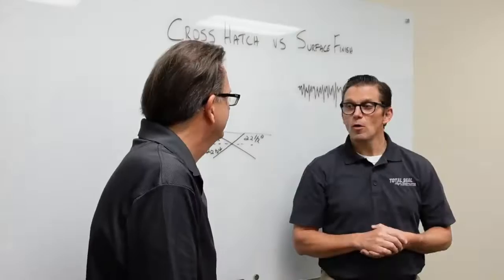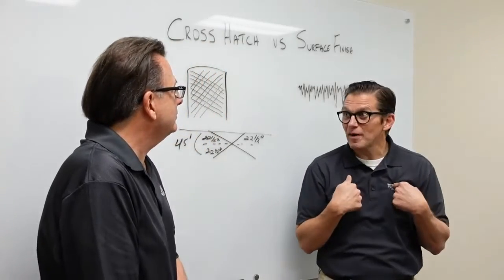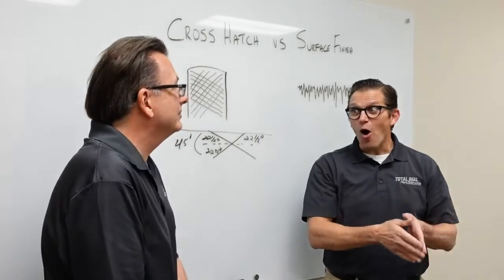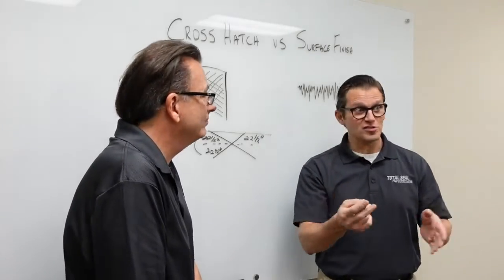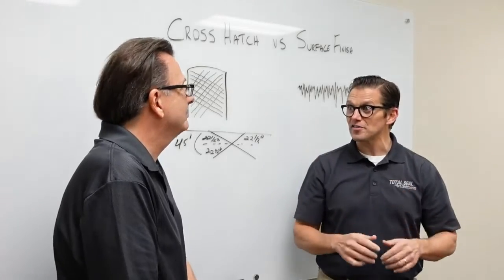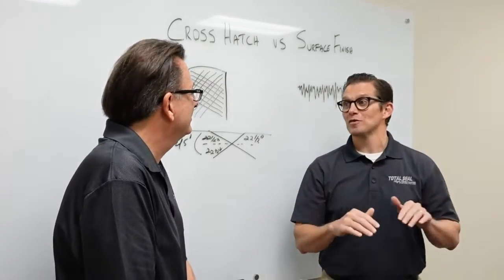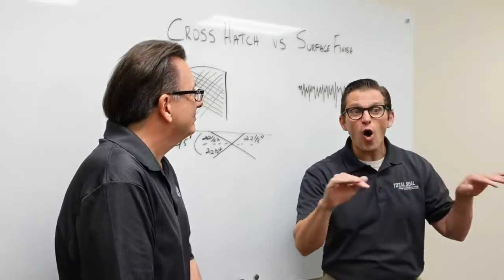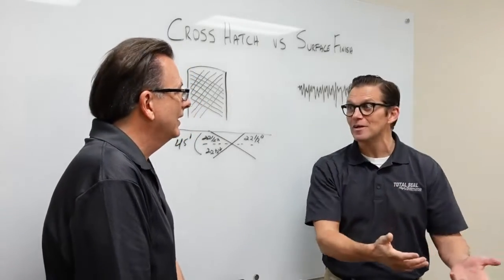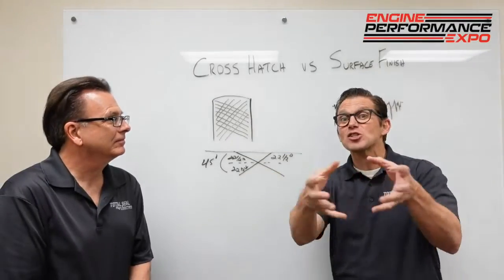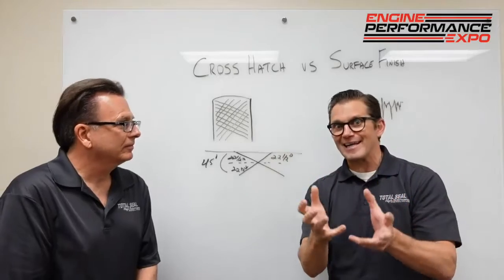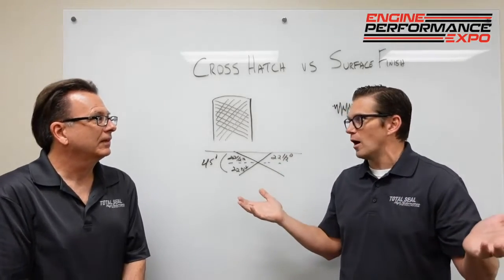This is about education. Like I said, my personal experience at Shavers with a little small block test engine: over 1,000 dyno pulls in 2 years on 0.7 millimeter steel rings, no loss of power. We were doing power testing all the time, so we could see what was going on. There's just no degradation. But we had the whole package right. We had that soup, the right ring, the right surface finish, the right cross hatch angle. It all worked together, and the performance was unreal.